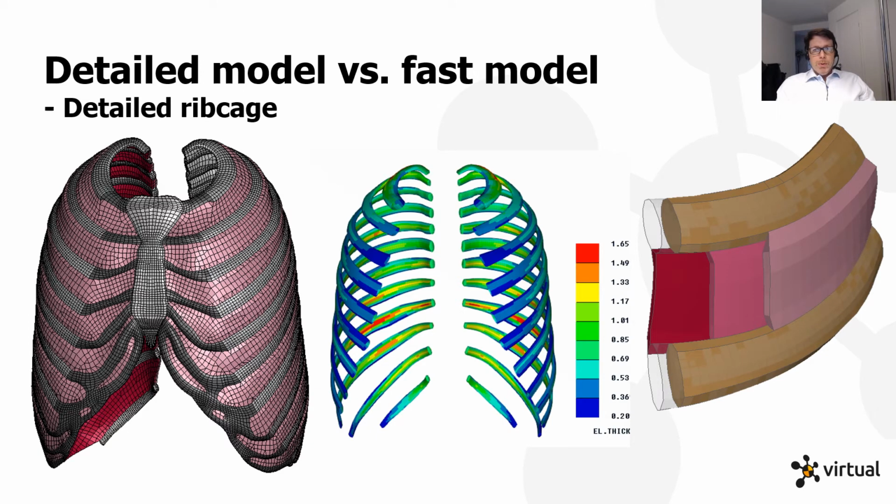Some skeletal body parts have been modeled in greater detail to enable tissue-based injury criteria. The first part is the rib cage that is modeled in a similar way as in the SAFER HBM. The cortical bone is modeled with shell elements and the trabecular bone and intercostal muscles with solid elements. The thickness of the cortical bone is based on average values from the literature.